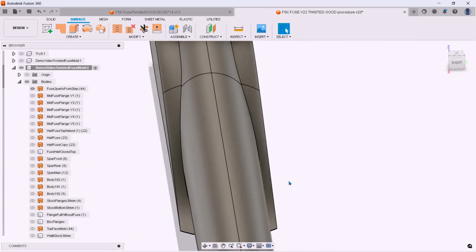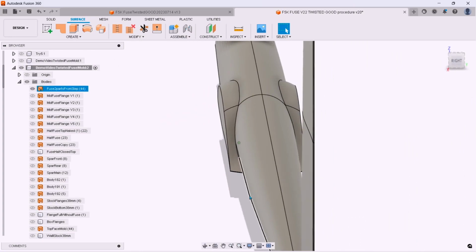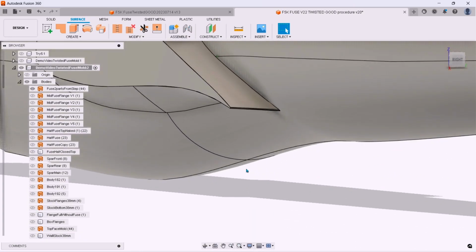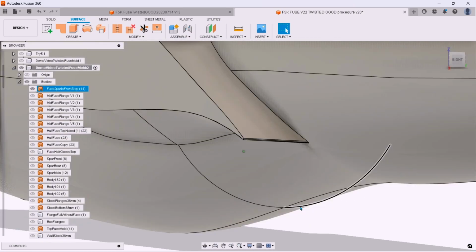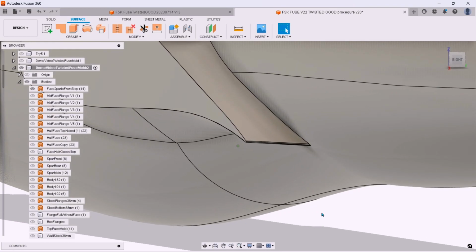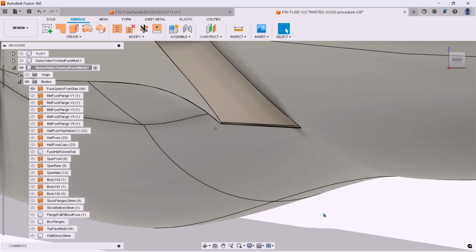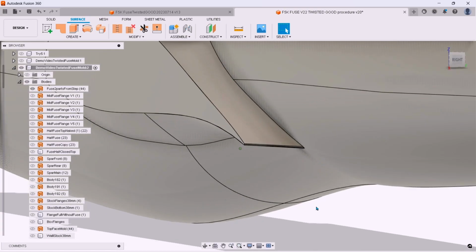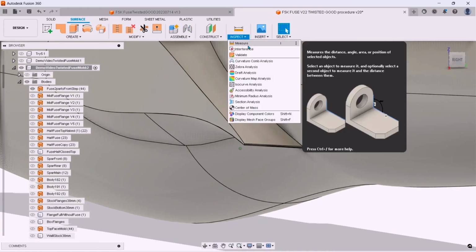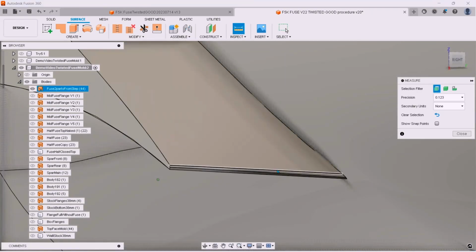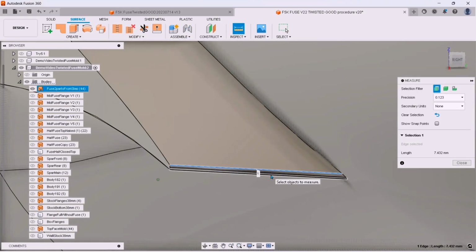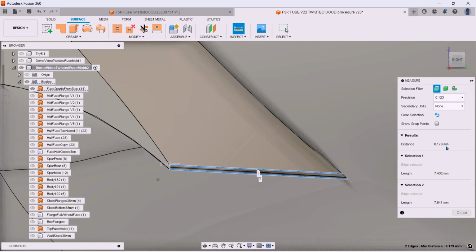But here I need to redo this because I have a little problem. Let me show you the problem. It's okay to draw some CAD file to make everything look smooth for aerodynamical purposes. But look, what is the height between here and here? So we have less than 2 or 10 millimeters. So when I go to the milling machine, do I have a bit of 2 or 10 millimeters?